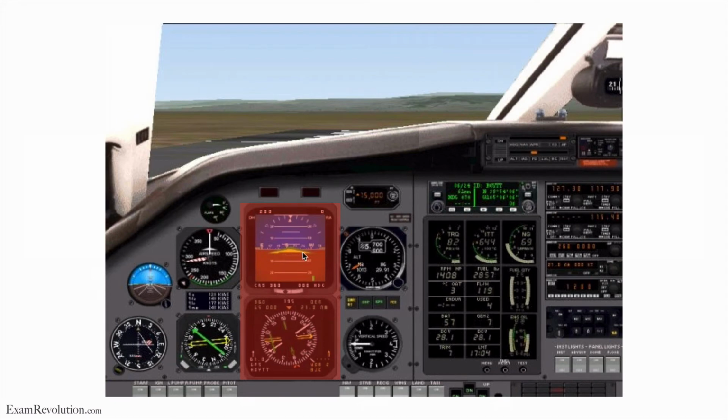You can see there's the aircraft, there's the blue part, and the green part that you see is called the flight director, or the FD, and we'll talk about that. And then the bottom screen is your HSI or your ND, your horizontal situation indicator, or your navigation display. And you can see your airspeed indicator, your altimeter, and all these things are still old school steam dials, so they are still operating in the old-fashioned way. There's no EFIS really incorporated in there.